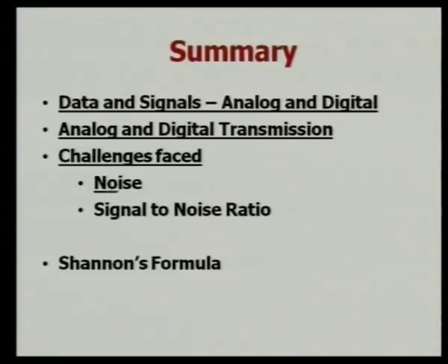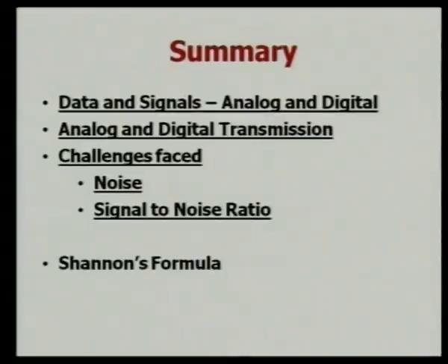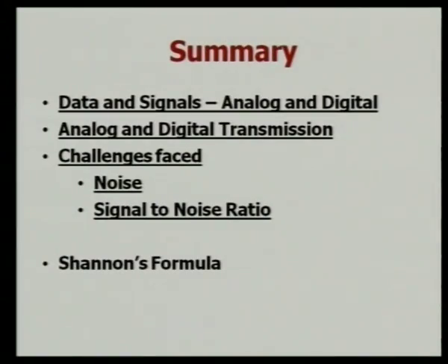When we talk of noise, we need to understand that we measure noise in terms of signal to noise ratio, and the signal to noise ratio has to be high in a system. We always need to design systems such that the signal to noise ratio is high. We also looked at how the signal to noise ratio can be used in order to determine the capacity of a given channel. Depending on the bandwidth, using Shannon's formula, we will be able to estimate the amount of data that can be carried on a signal. In addition, we also looked at what is meant by attenuation and how repeaters or amplifiers can be used to boost the signal strength.